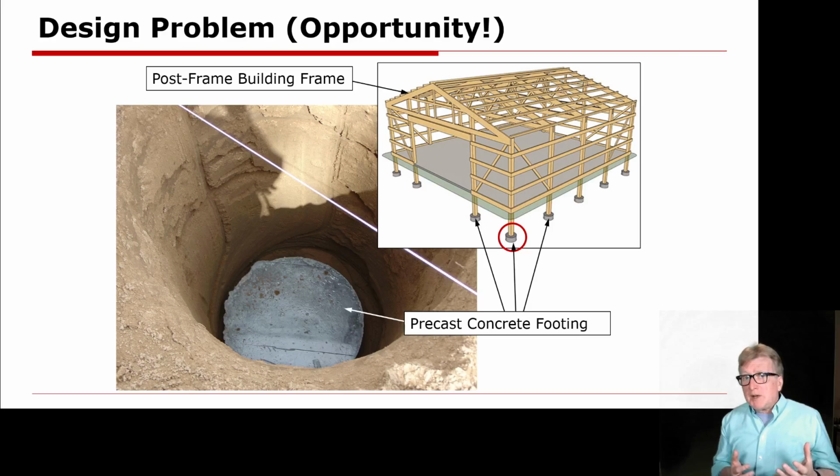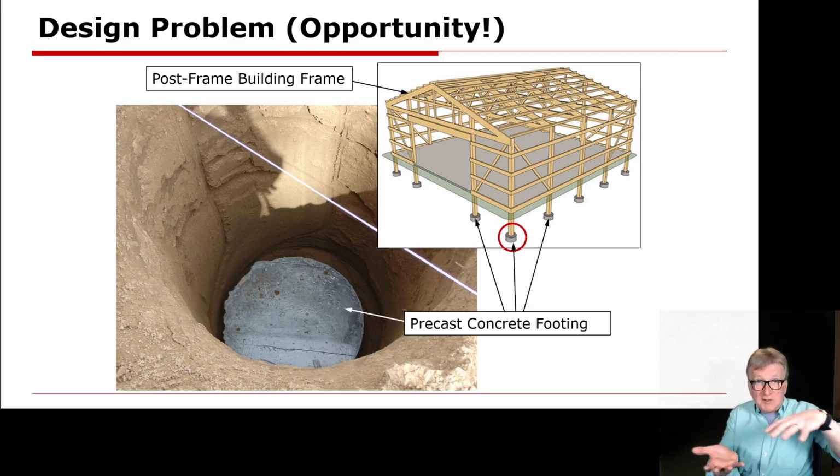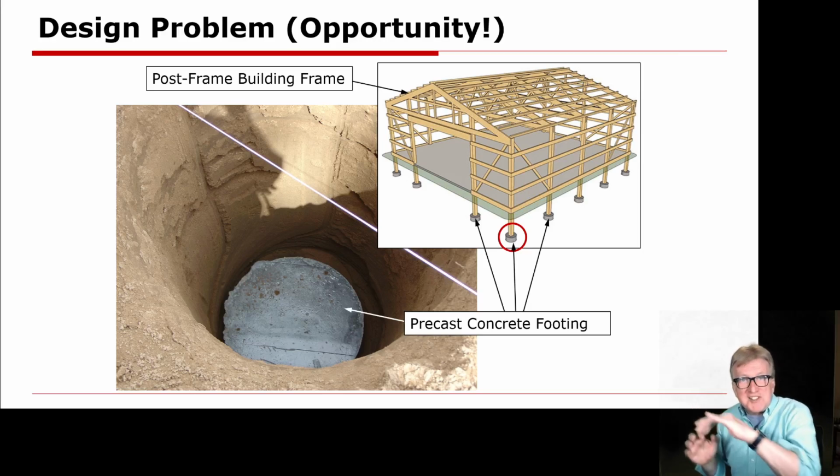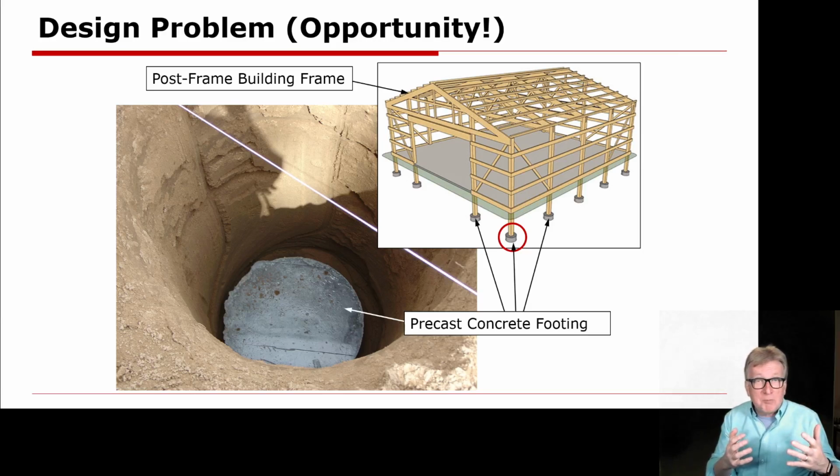The problem is, you can think about this. You have a 4 or 5 foot in diameter hole, and you're having to drop these discs into the hole weighing 150 to 300 pounds. You better make sure you do it right. When you drop it in there, you need to make sure it's level. It needs to go in square. If it's off center a little bit, or if it's dropped in not level, you're probably going to do damage to the side walls of the hole. So it creates all kinds of problems. And if you scuff the side wall, you're going to also crumble dirt and sand down into the hole. And then chances are that cookie is not going to land level. And it's also very difficult to get it back out of there once it's been dropped into the hole.